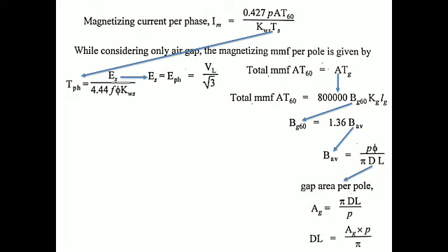It is also used in the I_m equation, the magnetizing current equation. So find the K_ws value. K_ws is calculated as the product of pitch factor and distribution factor. To determine K_p, it is cos alpha by 2. For alpha, the data is given, which means the Q value, slots per pole per phase, then a short pitch coil of 160 degree span.